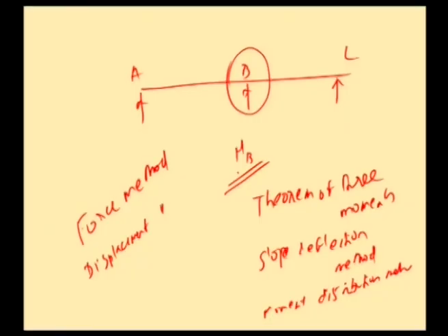In the force method, we will be treating the redundant force as the unknown, and finally, we will be getting the solution using the various theorem of minimum potential energy or virtual work concept. So, the strain energy method is an example of force method with which we can solve indeterminate beams.